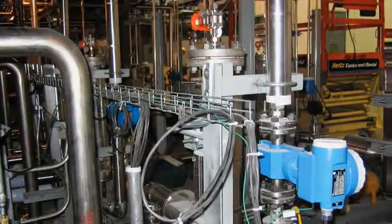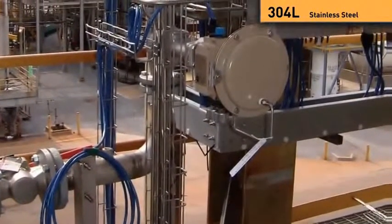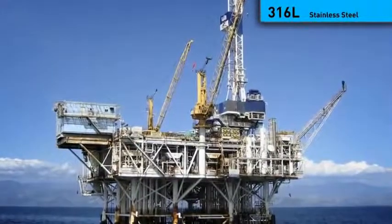Is the environment corrosive or does it have a special purpose? Chemical plants, food processing, or clean rooms are good examples of environments where our 304L stainless steel tray should be specified. 316L should be specified for installation near marine environments.